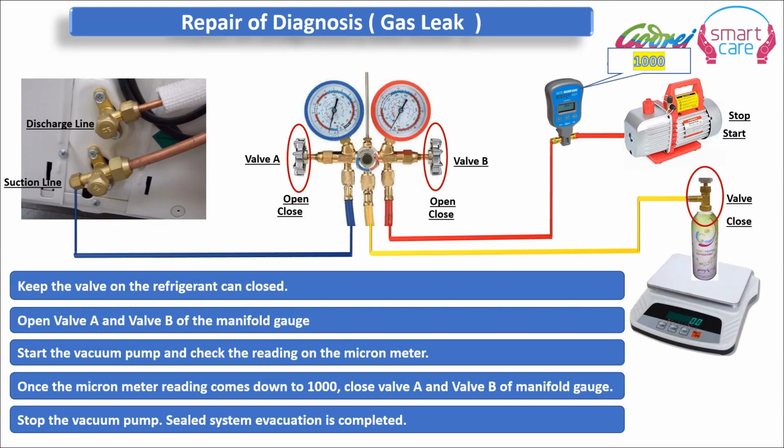You have to keep the valve on the refrigerant can closed. Open valve A and valve B of the manifold gauge. We start the vacuum pump and check the reading on the micron gauge. Once the micron gauge reading comes down to 1000, close valve A and valve B of the manifold gauge. Stop the vacuum pump. Sealed system evacuation is complete.